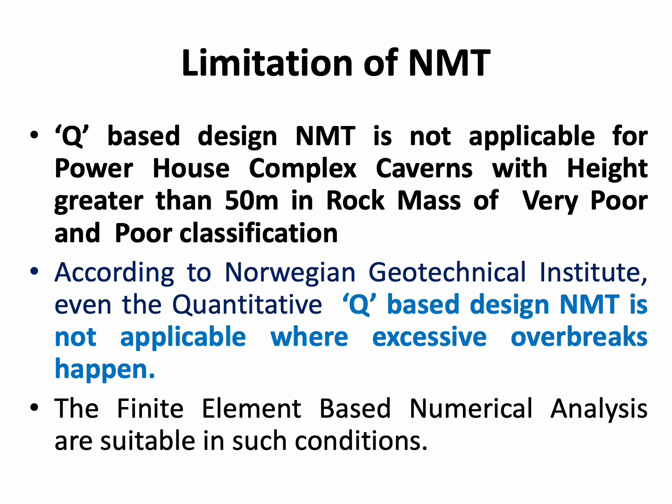The finite element based numerical analyses are suitable in such conditions where the Q-based design NMT remains inapplicable due to excessive overbreaks, or where the rock mass is very poor and of poor classification when the height of the caverns is more than 50 meter. In those circumstances, the finite element based numerical analyses are suitable only.